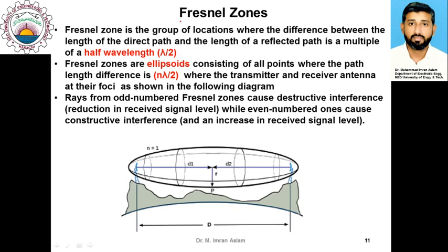Fresnel zones. What is the concept of Fresnel zones? Actually, the calculation that we did in the case of the ground reflection model was based on the propagation of a ray. So we assumed that the wave is propagating in the form of a ray, and we made our calculation on the basis of that ray.